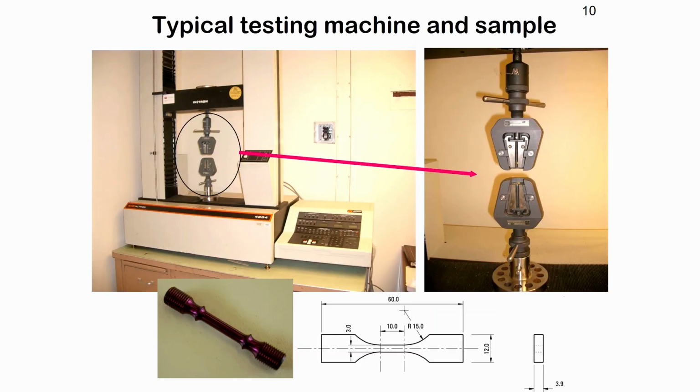So anyway, you have to start out with some sample. If we are talking about metals, usually you would create so-called dog bone specimens. These are either cylindrical or rectangular in cross-section with bigger dimensions at the end for you to grip onto, right? And the central test section is usually smaller, so you can concentrate, remember stress concentration? You can concentrate the stresses along the central thinner section so you can examine everything within that section.